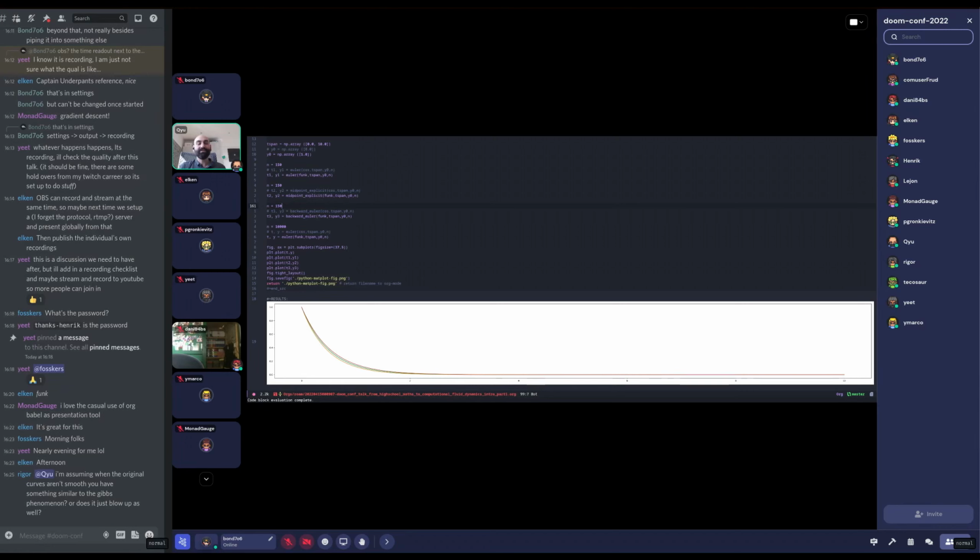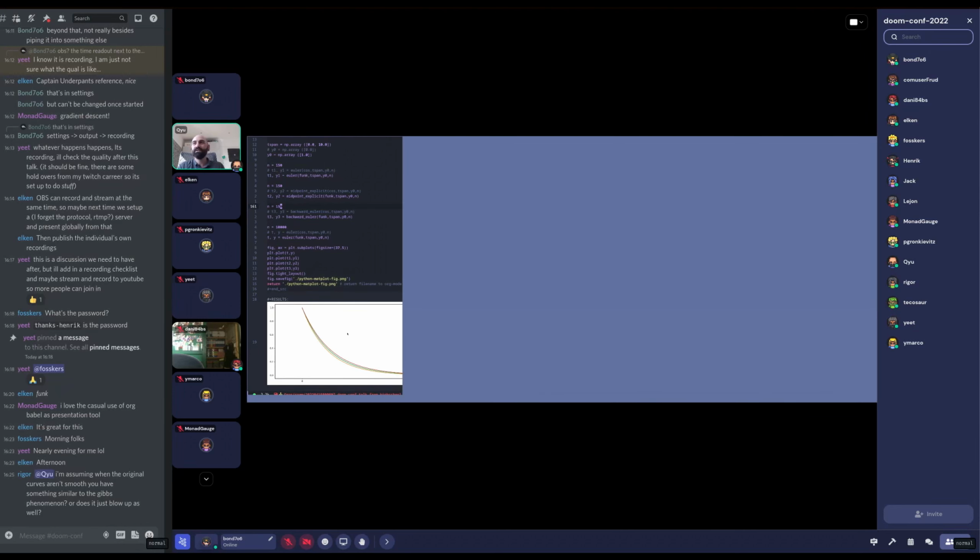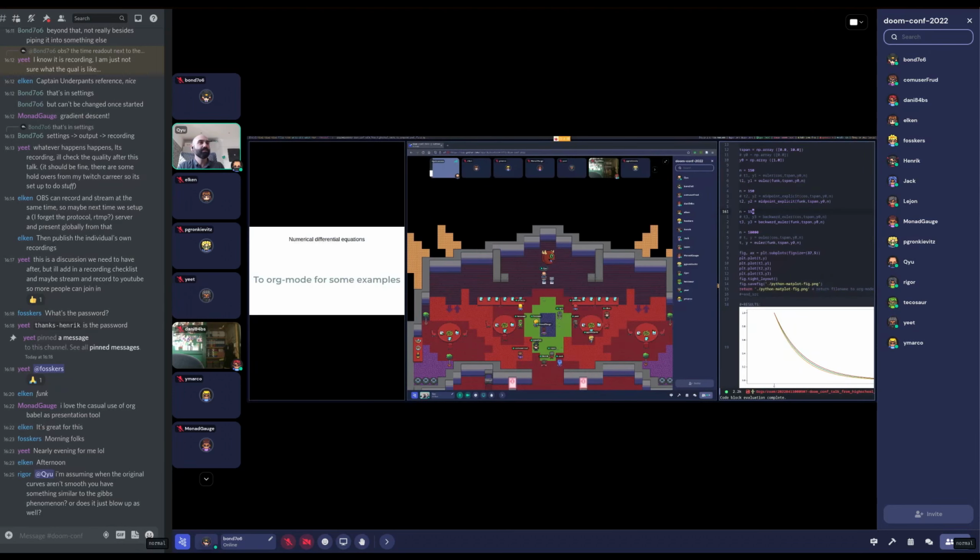So this gives us some kind of limits to what we can do. And when we're trying to solve massive, massive systems, sometimes we want to have the biggest time step we can get away with, because each computation takes a long, long time. And the cost of the nonlinear solver will be smaller than the number of time steps it would have to include in order to get away with a simpler method. So saying all of that, let's go back to our slides.